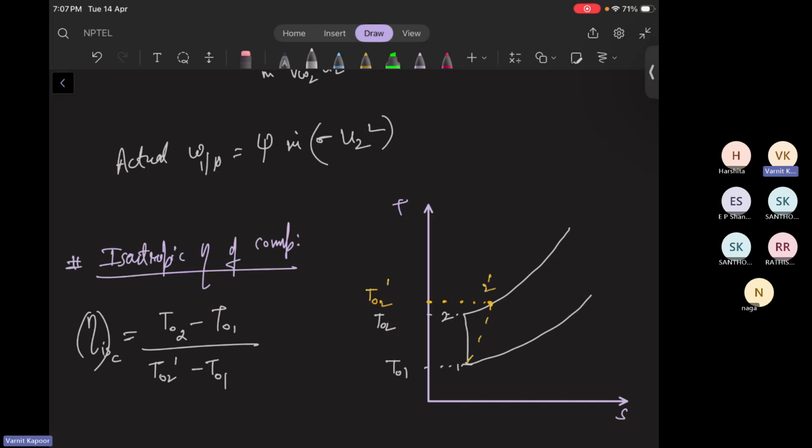There is also a scenario of pre-whirl in the compressor. As I've said, there are a lot of high stress scenarios happening. For compressors running at a very high speed, there is a possibility of shock waves at the inlet of the compressor. If the Mach number is greater than 1, then the fluid is given a pre-rotation with respect to a fixed guide blade at the inlet.